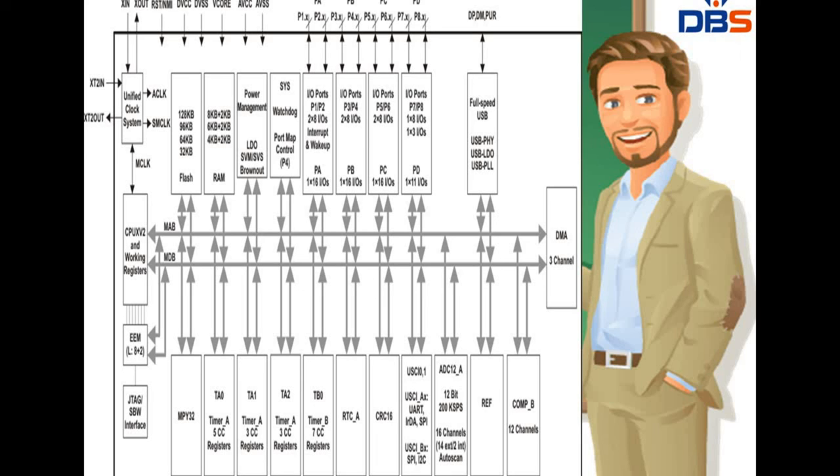Coming to the next one, MPY32. What is MPY? Multiplier 32 bit. This MPY32 is a peripheral and is not a part of the CPU. Its activities do not interface with the CPU architecture, and it performs signed and unsigned multiplication of 8-bit, 16-bit, 24-bit or 32-bit operations.